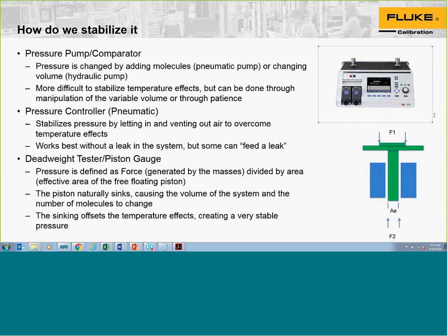Okay. Users do not perform detailed testing on their digital gauges. Is hysteresis less of a factor with digital pressure gauges? Always a factor. Hysteresis, once again, is defined as the difference in behavior caused by the pressure either going up versus going down.